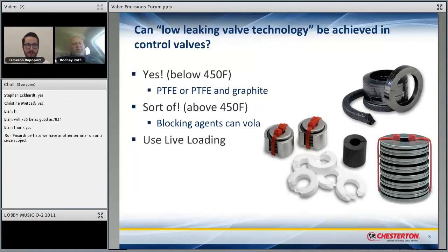Well, we've performed below 100 parts per million at 1,500 psi and 750 degrees. Thus, that's the top end of our 1622 warranty. Reality is, I never see those applications, because who's going to go out and stick a fugitive emission probe on a valve where the stuffing box is at 800 degrees?